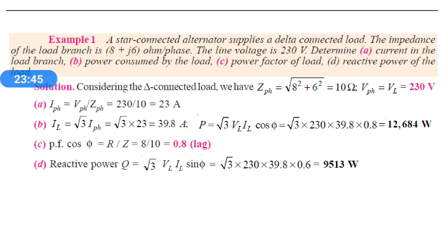So root 3 into 230 into 39.8 into 0.6. The answer is 9,513, not watts here, VAR, volt ampere reactive, or 9.513 kVAR.